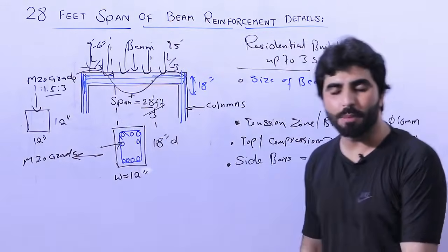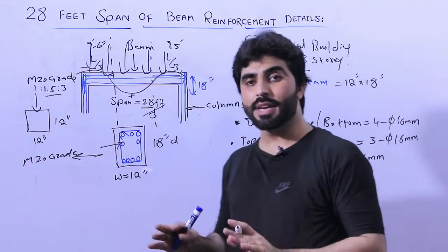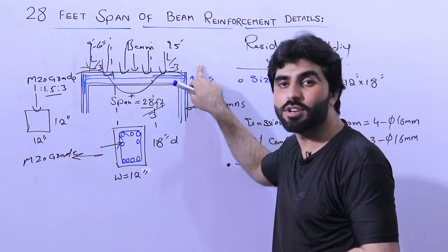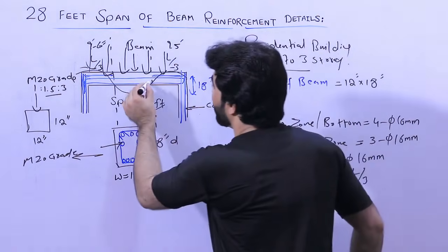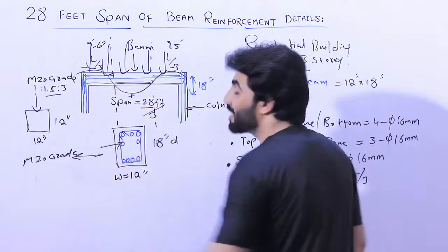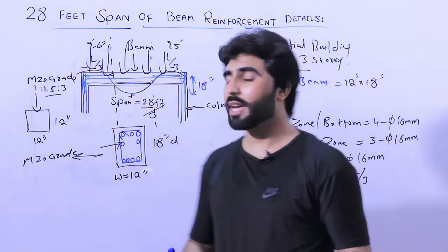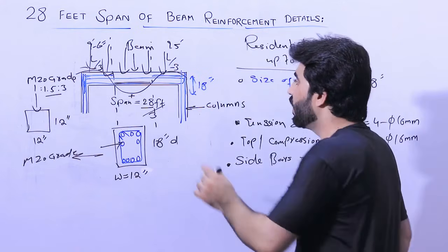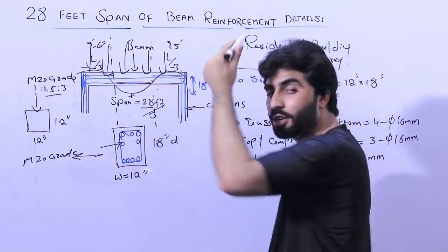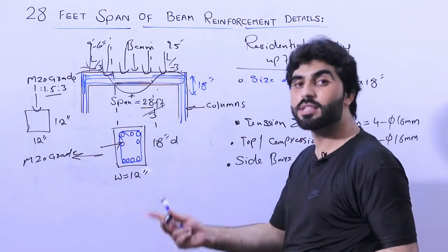To resist negative bending moment, provide extra steel rods or crank bar. To resist positive bending moment, provide extra steel rods here at the bottom, instead of overlapping. Okay. If you require to provide the lapping length, lapping is not allowed at the distance of L/3, because here we have also more chances of cracks. So here we should provide extra steel rods.